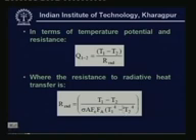But it so happens that in most of the practical problems, when the temperature difference is moderate, then you can assume the radiative heat transfer coefficient to be linear. That means we can linearize the radiative heat transfer and write it as a function of temperature potential and a resistance. We shall see later what is the advantage of writing heat transfer rate in terms of a potential and a resistance. Now let us look at the other very important mode of heat transfer known as convective heat transfer.